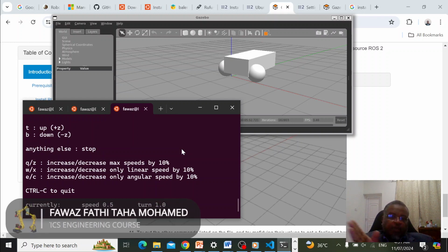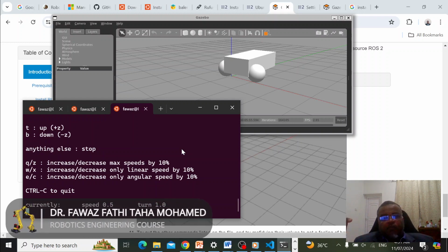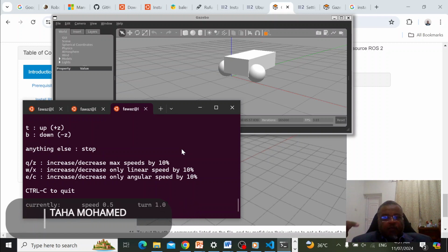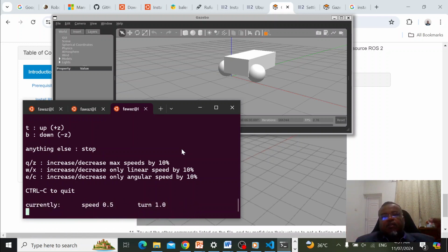If I want to make a rotation to the right, I have to move one of the wheels with higher speed than the other, and so on. So here I have two joints, and we are going to move this robot in 3 dimensions. So this is always under actuated because we have 3 degrees of freedom and we have just 2 joints.